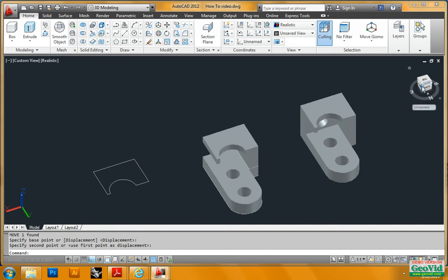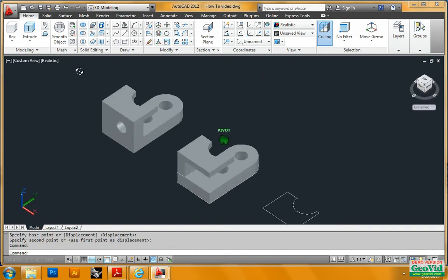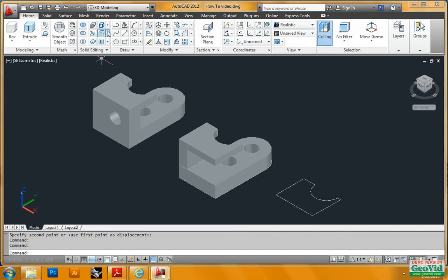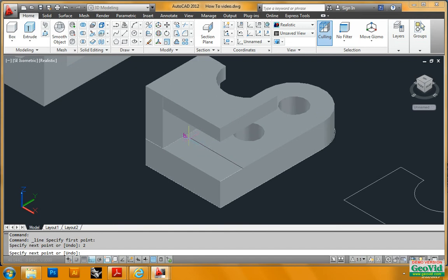So if I scroll around here, you can see that I have to do the back part of it, which also has a hole in it. So to do this, I'm going to draw another rectangle back here. I'm going to do it by creating 2 lines, so it's 2 units, and then I'm going to make it perpendicular, and then once again I'm going to push pull, and you can see it broke itself up, and I'm going to push pull it right up to here.